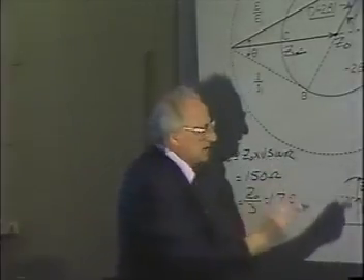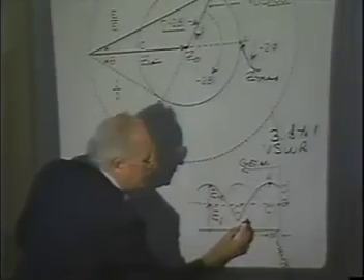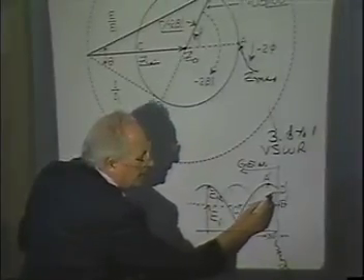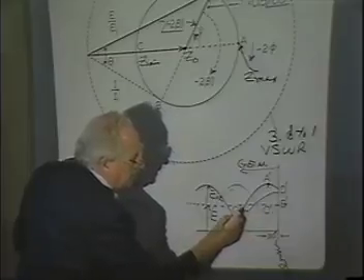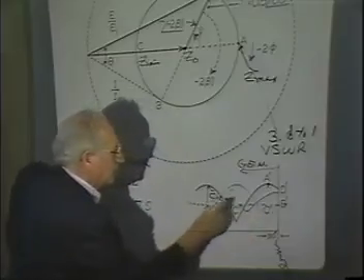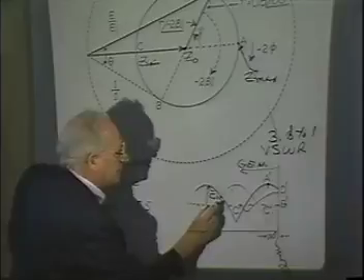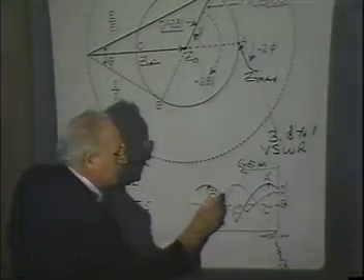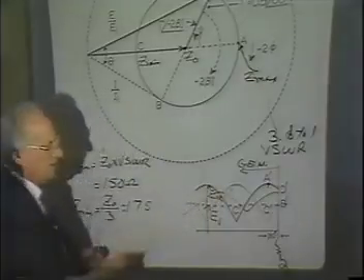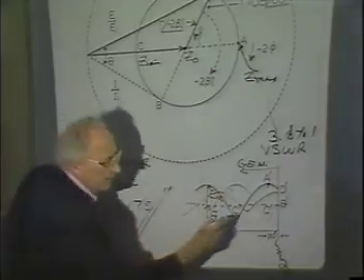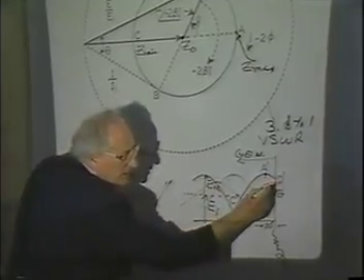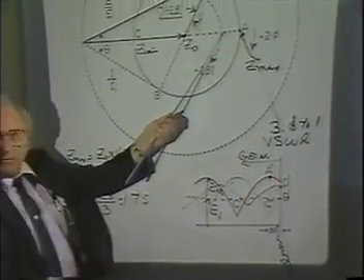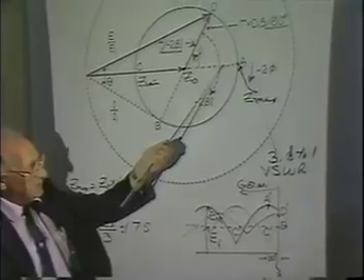Now notice this. If I do this, and I put up something greater than Z0, like this. Notice what's happened here. I've put a pure resistance here, which puts me someplace in here, okay, not out here at 150, but in here someplace.